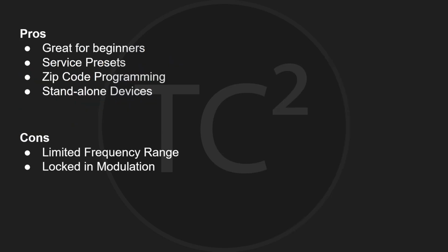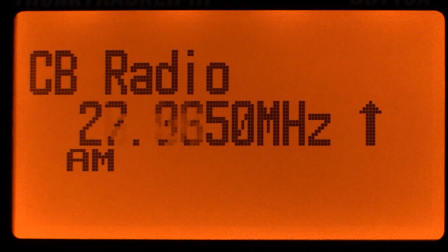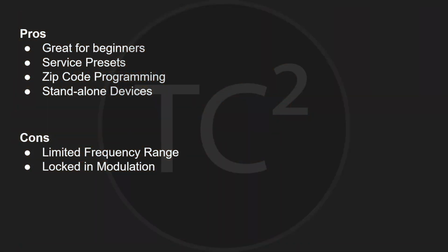The next one is going to be their locked-in modulation. Scanners are locked into specific modulation depending on the band you're on. You're generally locked into AM mode for the civilian and military aircraft bands, and also AM for the CB and 10 meter ham radio bands. Everything else is typically locked to FM.